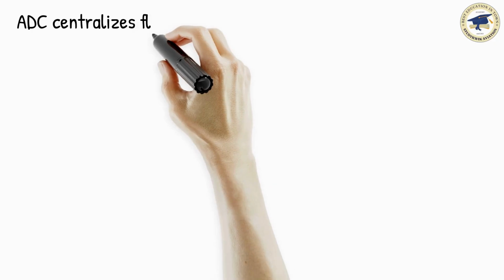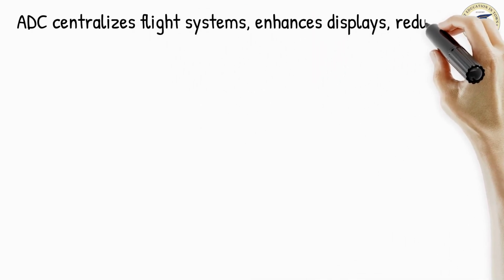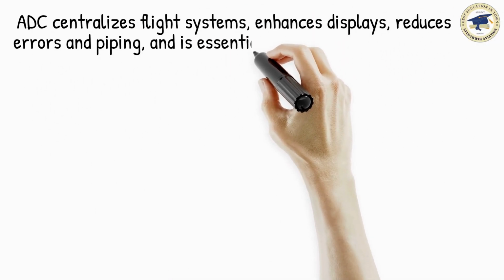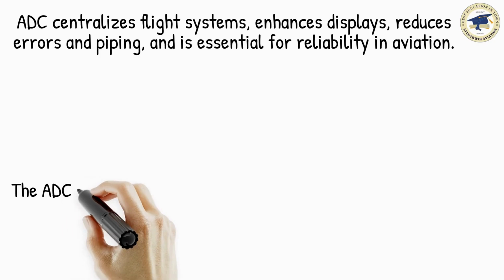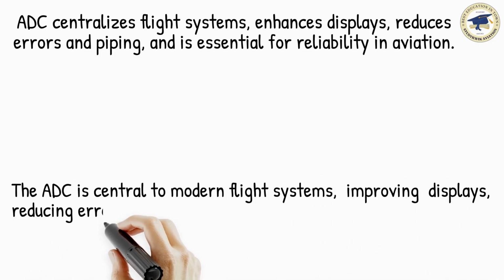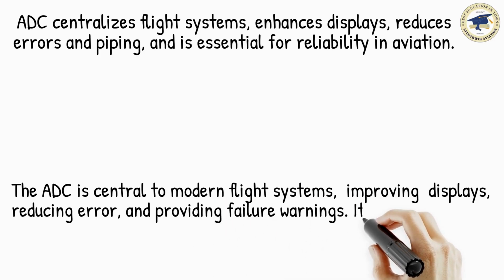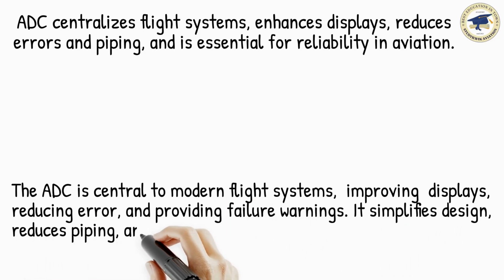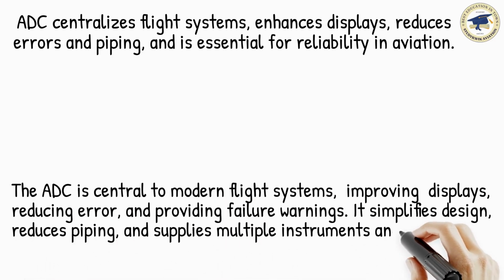The ADC is central to modern flight systems, improving displays, reducing error, and providing failure warnings. It simplifies design, reduces piping, and supplies multiple instruments and systems. Electronic ADCs are reliable, accurate, and essential in modern aviation.